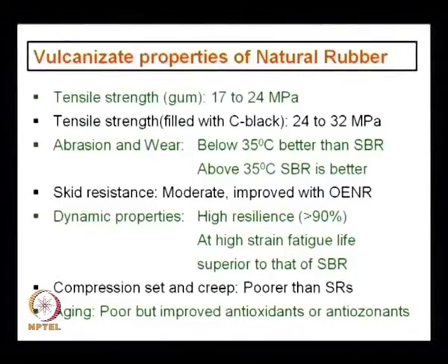Stress your load, applied load, then after application it is released. So, continuously it is application and release, application and release. So, this kind of cyclic load is there. So, this is called dynamic stressing, and that is actually evaluated in the laboratory in simulated condition by flexing machine or fatigue to failure machine. That machine is there in our department. If you are interested, you can see there.